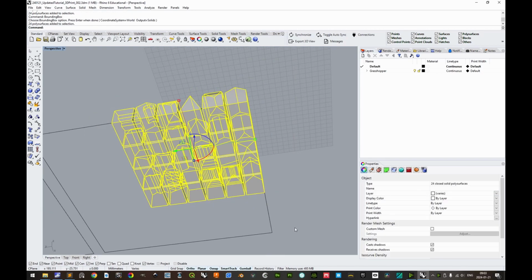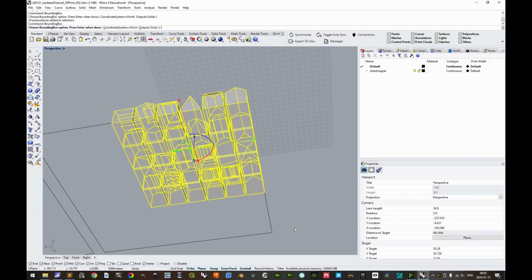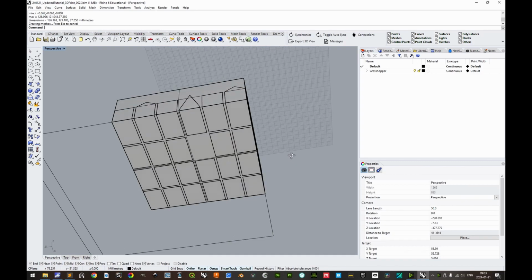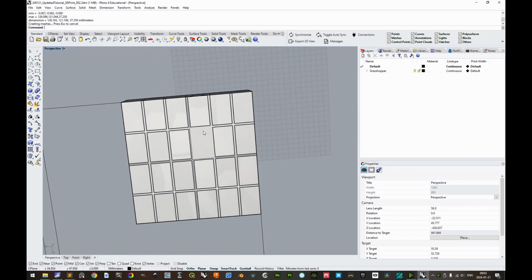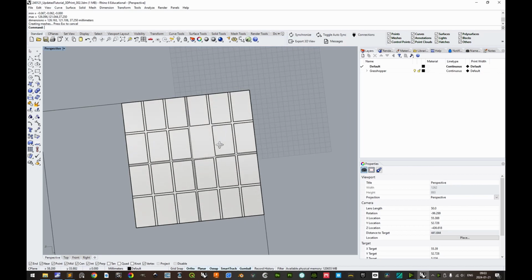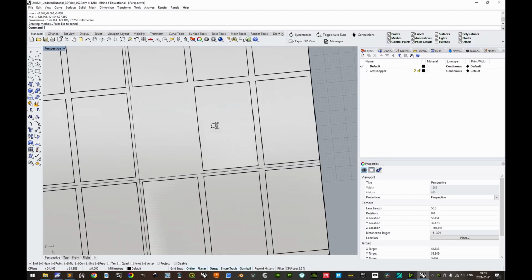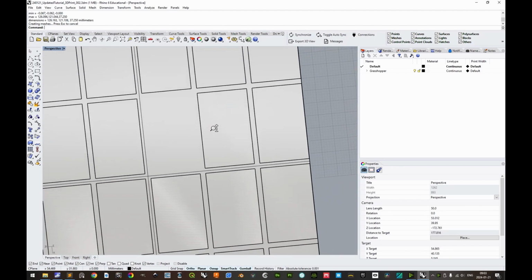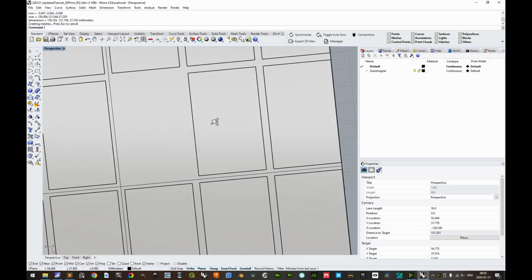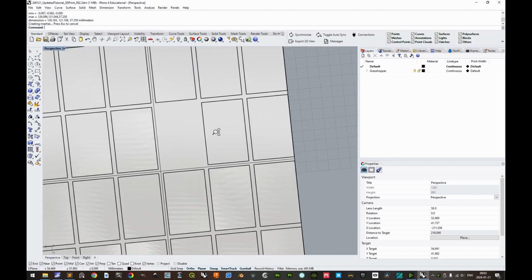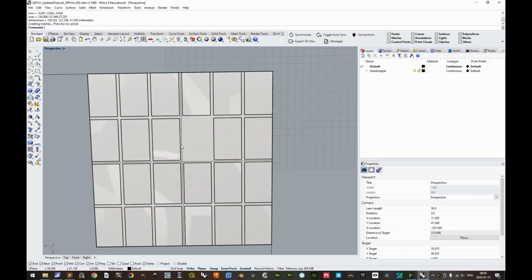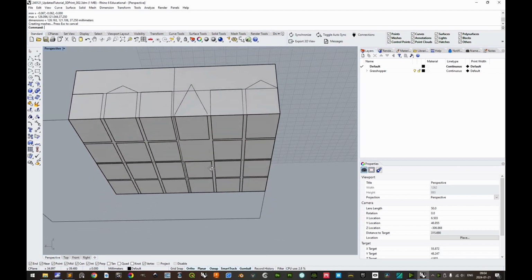This is most easily evaluated by doing a bounding box. Press enter again to confirm that you want world coordinate dimensions. And see if there are any model bottom surfaces that are not Z fighting, intermittently clipping through. Z fighting, which you see here, means that the bottom surface of the bounding box is co-aligned to the bottom surface of the object, which is a good thing. It means that they are horizontal to each other. If any model has its surface not Z-fighting, it might mean that it is erroneously placed along the vertical Z-axis.